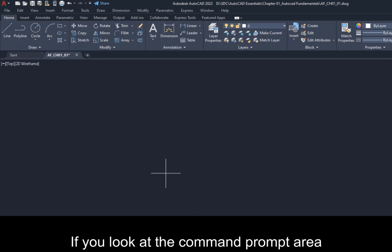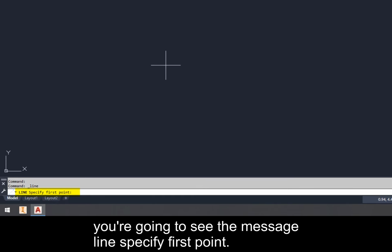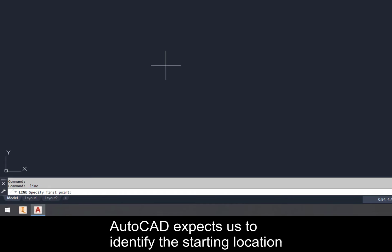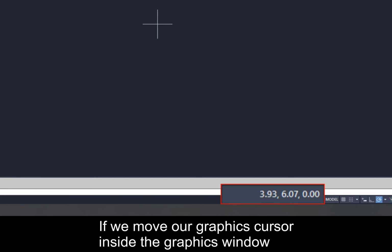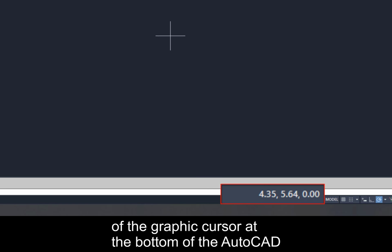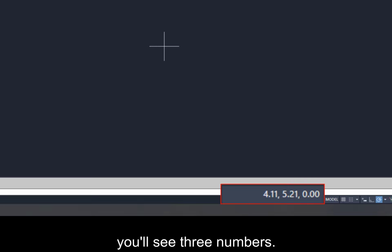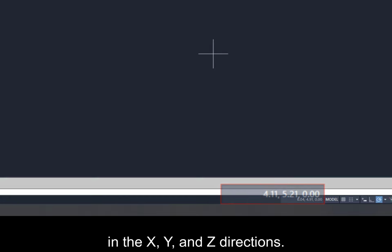command. If you look at the command prompt area near the bottom of the AutoCAD drawing screen, you're going to see the message line specify first point. AutoCAD expects us to identify the starting location of a straight line. If we move our graphics cursor inside the graphics window and watch the display of the coordinates of the graphic cursor at the bottom of the AutoCAD drawing screen, you'll see three numbers. These three numbers represent the location of the cursor in the X, Y, and Z directions.